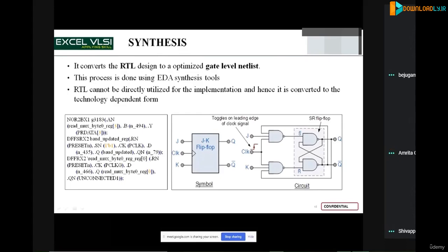Okay. Now, in Verilog, you might know already that you are instantiating a component. When you have multiple blocks in the top level, even in the architecture I explained, there will be multiple blocks, and these blocks will be instantiated in the top level. In the netlist, you will see all the Verilog code has been translated into gates, gates or standard cells. The standard cells could be combinatorial circuits and also sequential circuits like flip-flops.